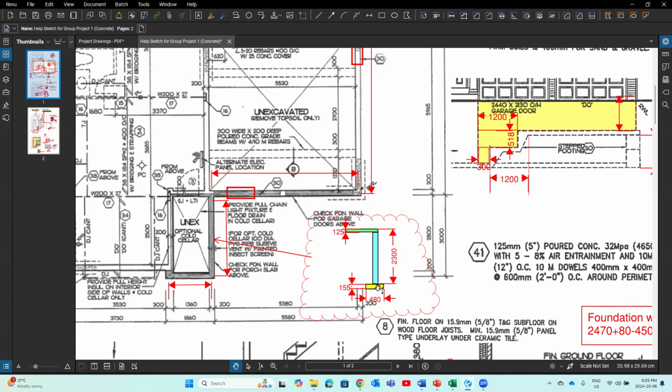The length of this wall is this around, right? If you want to get very accurate information, you will realize this wall is slightly thicker. You may need to adjust that. Formwork is okay, concrete is a bit different, you need to add a little bit here. Understand that? So that's how we calculate formwork.